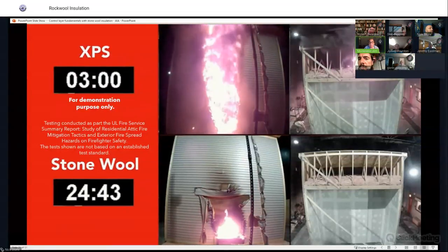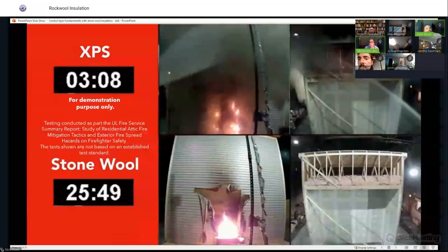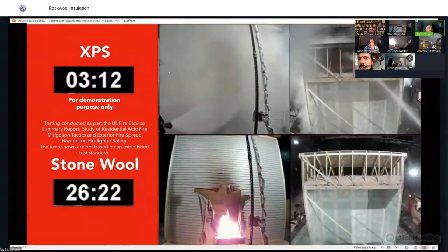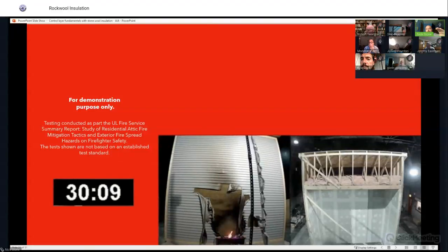Yeah, so all stone wool material is going to be a dark green in color. It's going to have a lot more density or volume to it than your fiberglass materials. If you were to grab that rock wool and physically press on it, you're going to find there's a lot of resistance. You almost can't flatten rock wool, whereas fiberglass you can almost pancake flat.